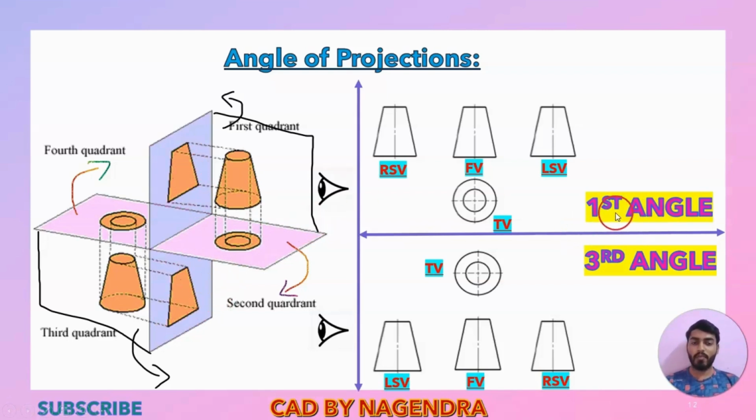So in first angle of projection, straight on top we will get the front view. Under that, if we tilt here, we will get the top view under that front view. Then this right side plane, again we are opening in 90 degrees. We are tilting here also in this direction. So this plane will be specified like this and the same shape we will get here. It means in first angle of projection, the front view will be on top. Under that you will get the top view.